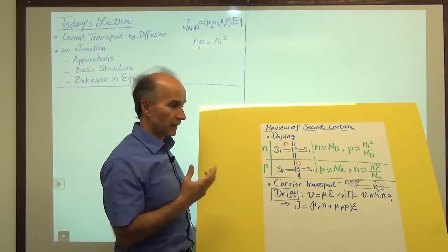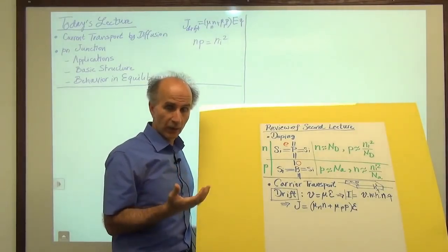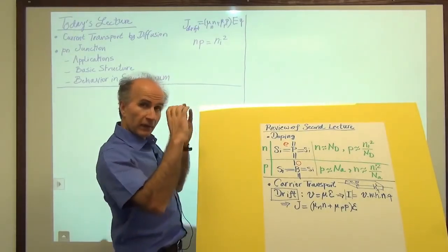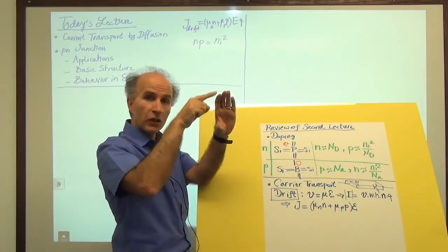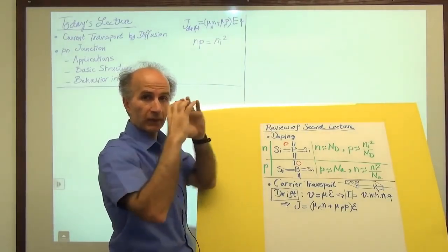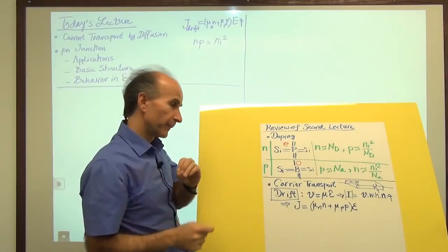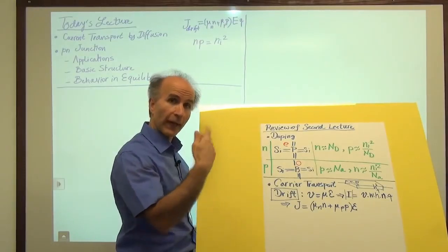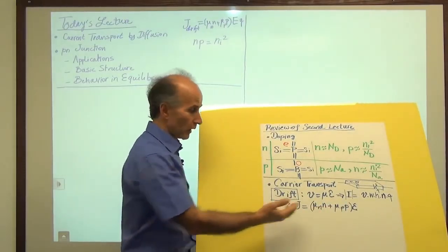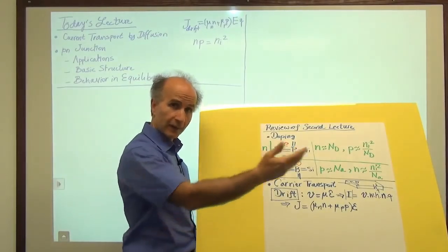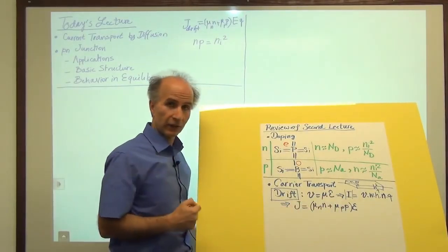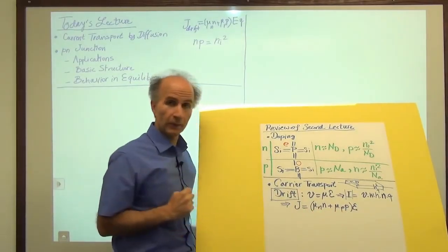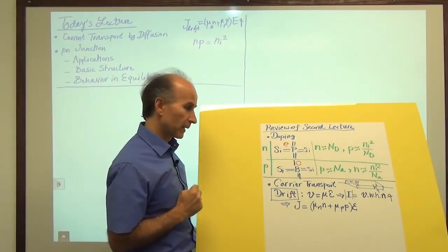And we saw that in semiconductor physics, we generally would like to express the currents as current densities. That means the amount of current that passes through one unit area of the object, so 1 square centimeter, for example. And that would be J, and is given for both electron flow and hole flow by this expression. Here we are assuming that there are some free electrons that carry current, and there are also some holes that can carry current. Now, one might be much less than the other, but in the general case, we need both of these terms multiplied by the electric field.